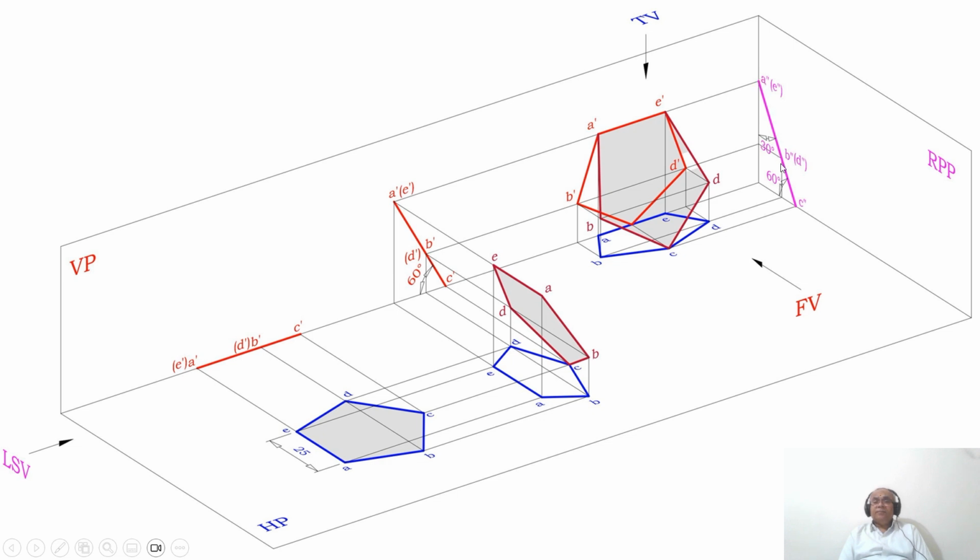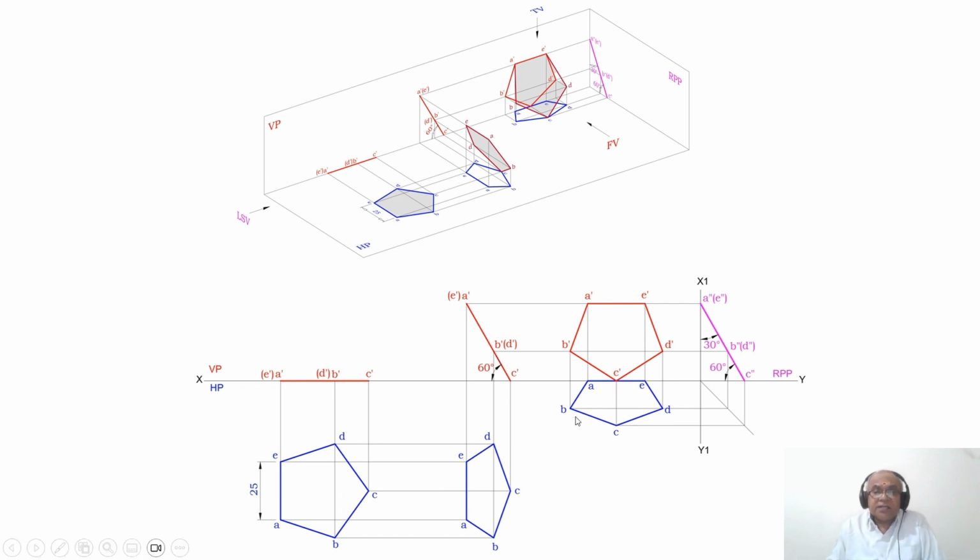Therefore, you are getting a line in the side view. One should do that. Now, how will I be able to draw that in two dimensions? As he says, the corner is resting on HP and the side opposite the corner touches VP. That means AE should touch VP. At present, A dash E dash is parallel to HP and perpendicular to VP. Since I want to keep this side on VP, and now this side is perpendicular to VP, I have to make it parallel. So how can I make it parallel? By rotating in the clockwise direction the second position top view.